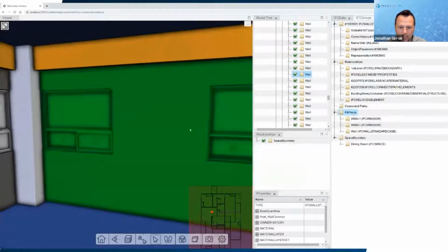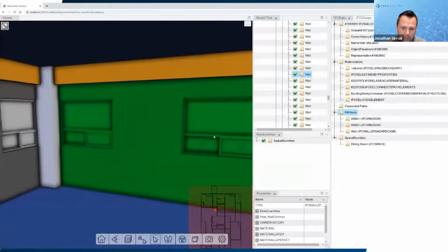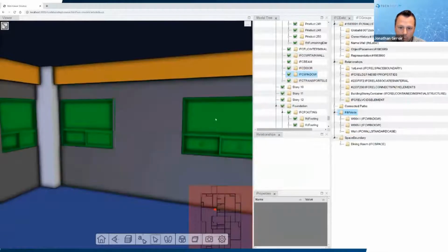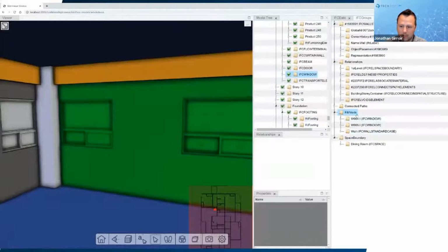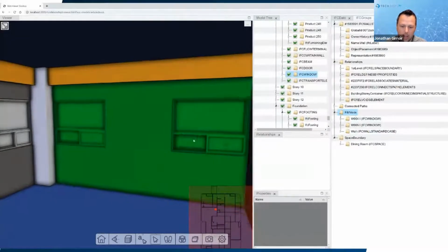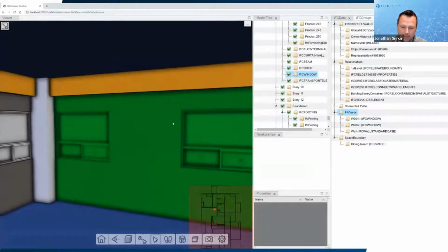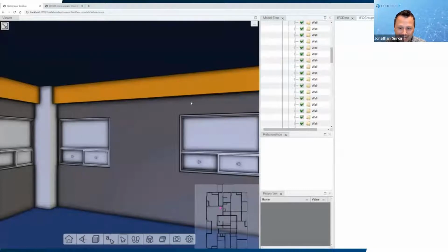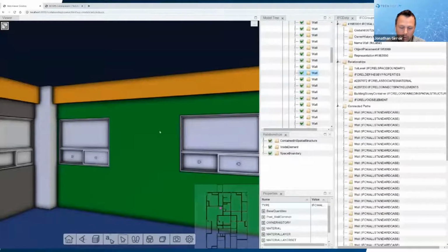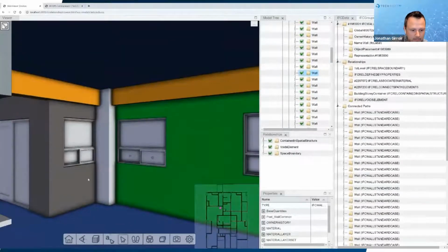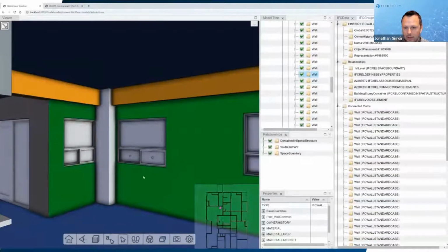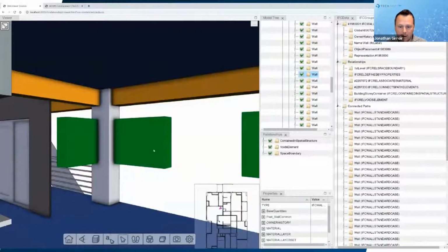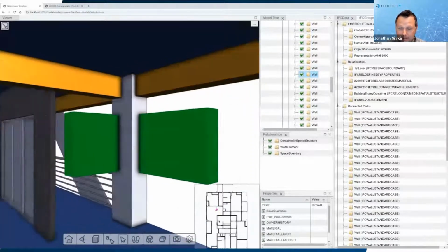Not only that, but we can select, let's say, another wall here, the adjacent wall, and say for these void elements, these holes, what is the construction geometry for that? And so in just a second, we're going to show those different pieces of geometry, not visible normally, right? So it's not part of my model, but it is contained there in the IFC file, and then we're able to use that as well for further analysis. And so there you have those windows now, the construction geometry for that.